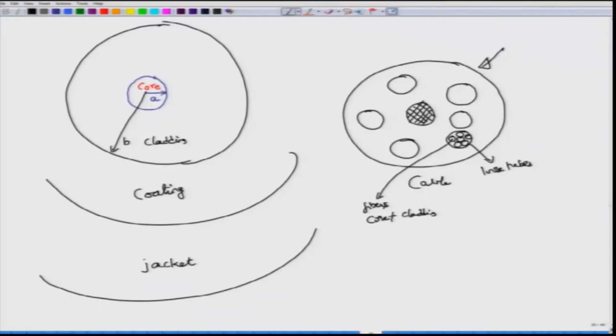Of course, the cable also has additional things, not just holding the fibers, it also gives all the fibers a mechanical support, right. I mean, you might lay a fiber cable underground crossing one road to another road, but then you have a concrete road on top of it where the vehicles actually keep moving, then if you just had the fibers below, these fibers would not be able to take that mechanical stress, they would just break. So, instead of that, you encapsulate them with thick cables, and these cables themselves are encapsulated in bigger cables. So, you do need to take care of all those issues, because you want the fibers not to break, because you have to use these fibers for communication.